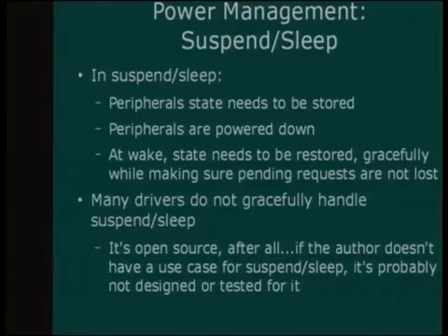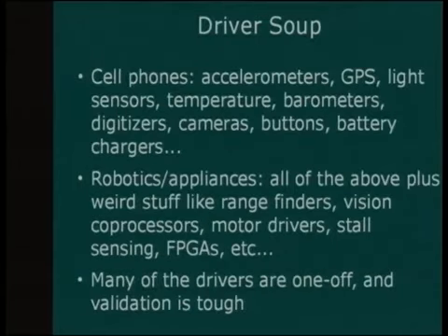Suspend sleep is painful. One of the troubles of being open source and embedded is that people write a driver, they check it in, it's great, but they didn't include suspend sleep support. This is a very, very frequent problem I have. So we end up taking drivers for different elements and we have to refactor them to deal with the fact that sometimes you want to actually turn off the peripheral while Linux is still on, power on the peripheral later, restore its state, and have it all work correctly.